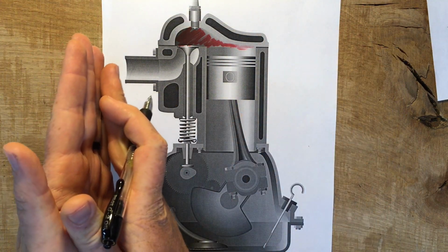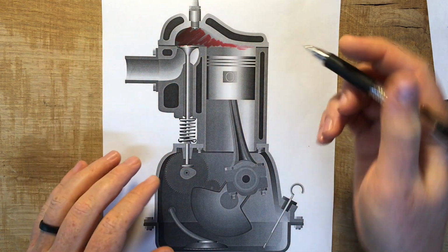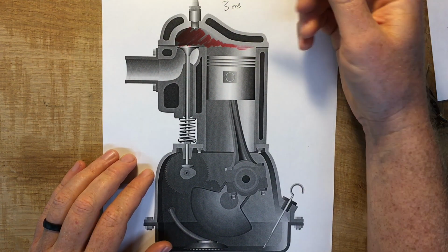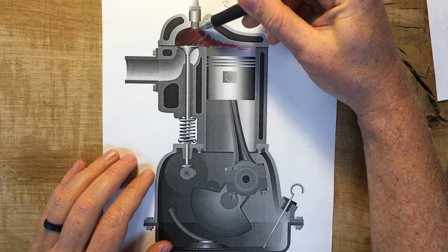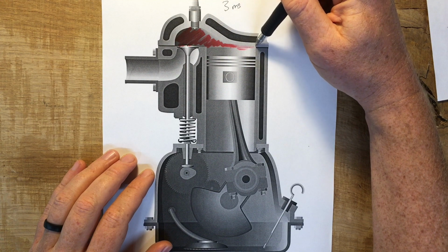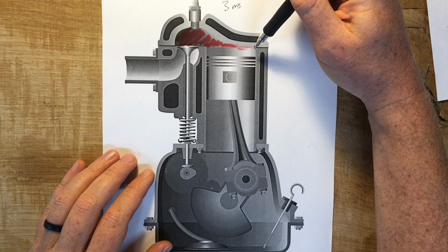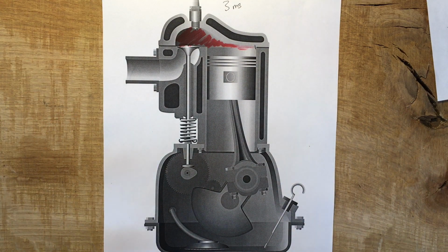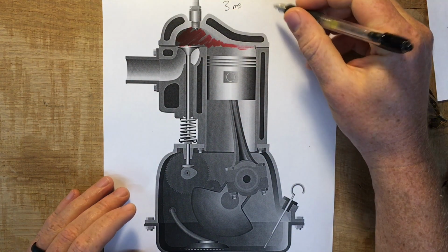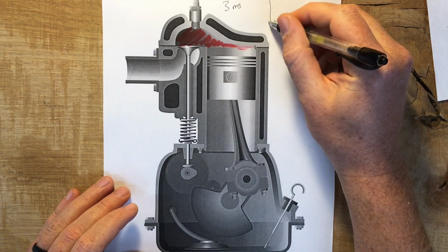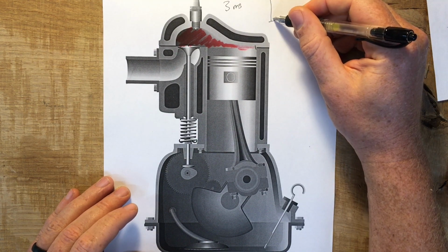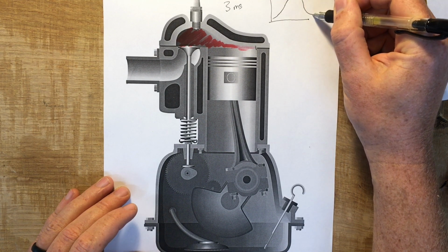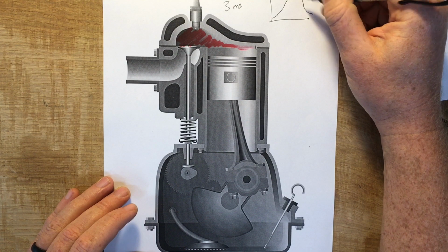People often think of gasoline as exploding instantaneously in the combustion chamber. But in fact, gasoline burns over a measurable period of time. The flame front takes about 3 milliseconds, roughly, to get from the spark plug to the edges of the combustion chamber. In other words, to burn all of the fuel-air mixture. As the gas burns, the pressure inside the combustion chamber starts to build up into a curve, like that. And then it peaks, and drops again.